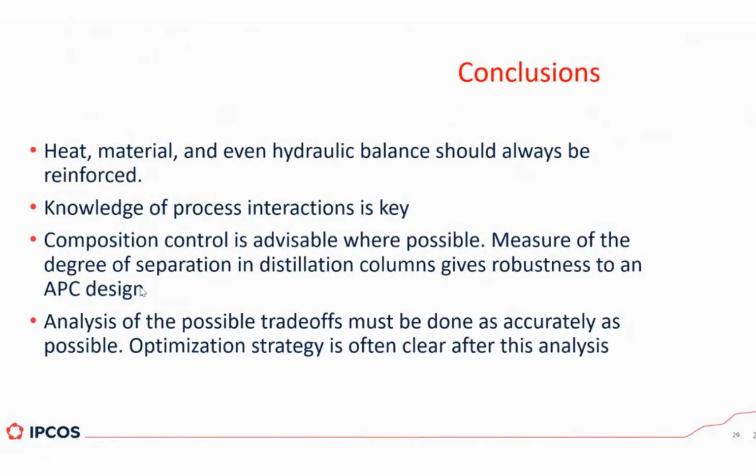Preferably analyzers, obviously, but if not, sometimes we take care of it using the lab results, but you need to have a reliable way of getting that. And even if you have lab results, you need an estimator that estimates the value in between results, because the control doesn't stop. You need to do control all the time. You cannot just adjust every 8 hours, every 12 hours, every 3 days. For the control to be strict, you need to have constant feedback, let's say. Yeah, good point.